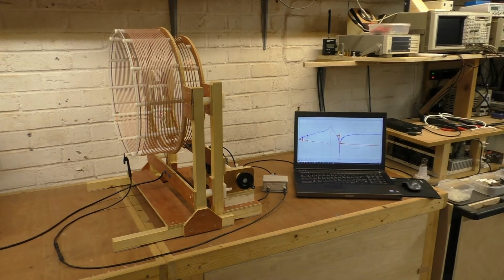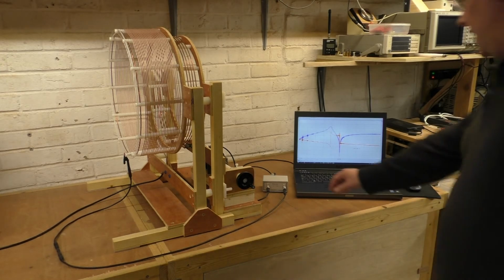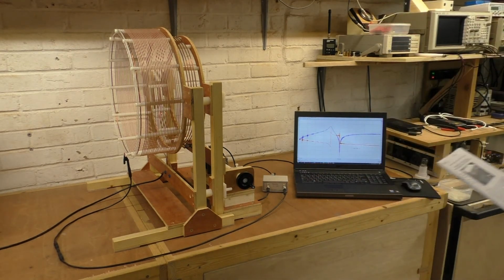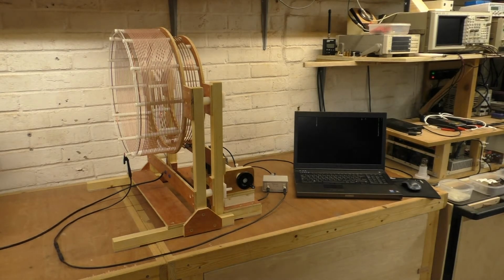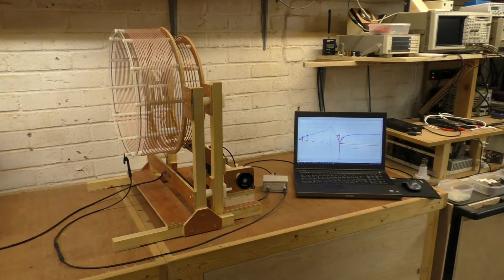The maximum safe input voltage into both ports is basically an RF voltage equivalent of 0 dBm, in other words a voltage into a 50 ohm load, or basically 225 millivolts RMS across the measurement range.